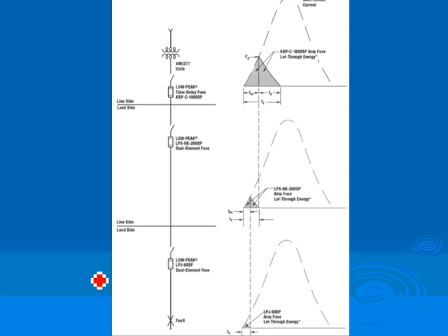That guy will trip within a quarter of a cycle, like you can see here. The circuit breaker, and that's where the fuse guys become a big deal. The circuit breaker guys will trip within 3 cycles. Here's one cycle, and they will go up. Here's another cycle, and here's a third cycle. So imagine, a circuit breaker will wait up to this point to trip, versus a fuse will trip half of this one right here. Can you guys see the difference? Who cares? This means that much energy is going to be baking and shaking your switch gear, or that much energy.